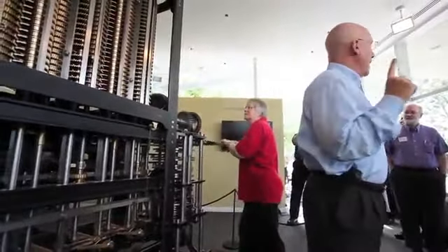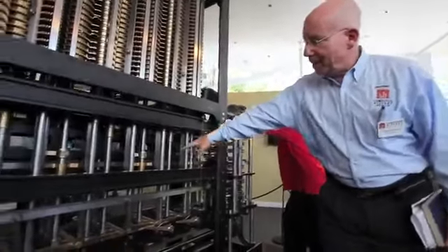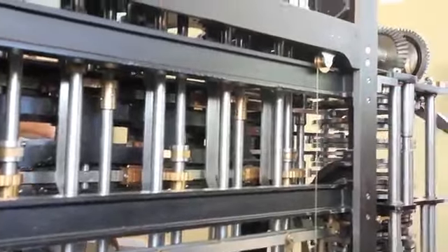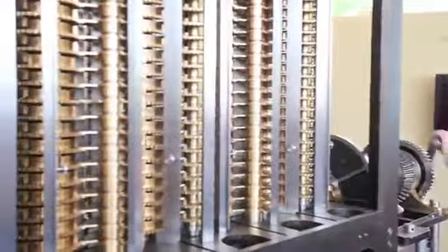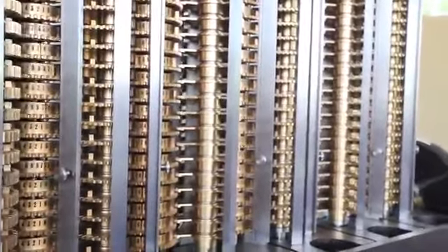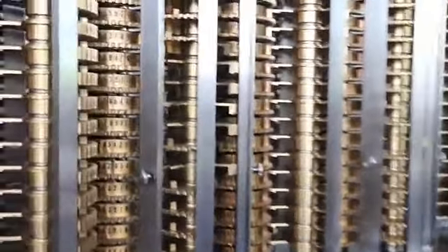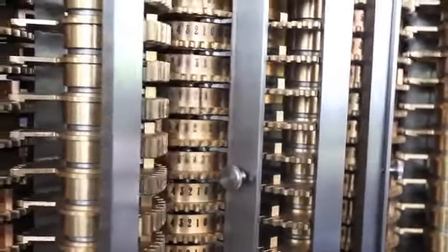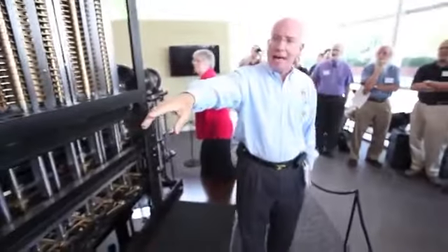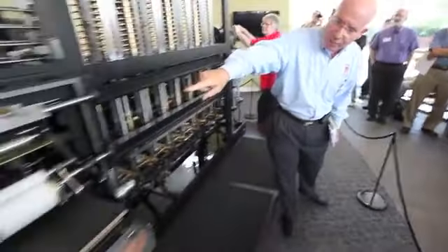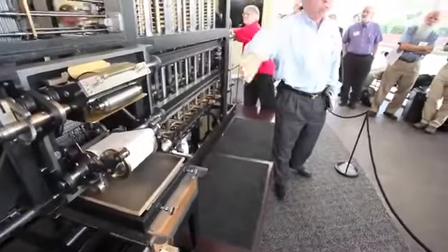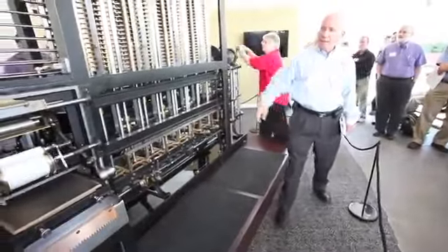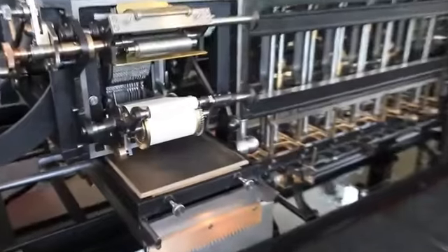You will also notice this clanking sound. That is the sound of these big interlock blades that run completely up and down the column, snapping in, because when you don't want those columns to rotate, you don't want them to drift in between 2 numbers. So that lock comes in, locks up the column, resets it completely, so you have integer digits on every column. And then you will see the print cycle happen. The type is going to rotate in a second. There's the rotation, print, stereotype, the tray index is in. Watch the next one come up here. There's the rotation, the type, ink, print, stereotype.